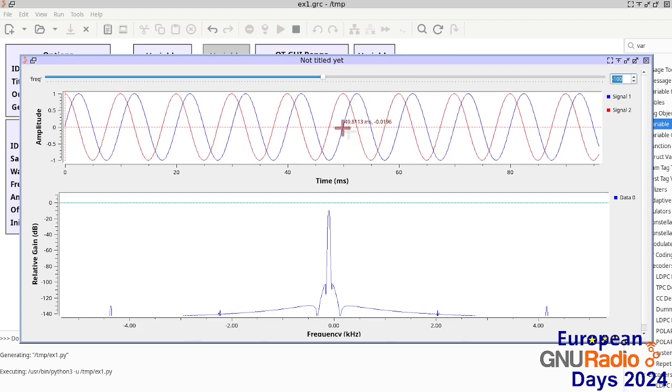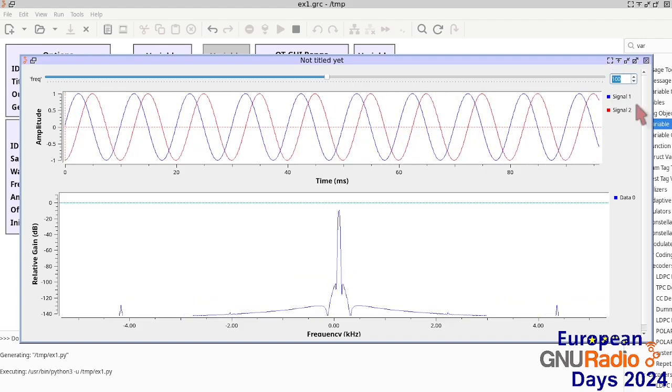So we have something which is a cos plus j sine, which matches the algebra of a complex quantity. And we see that a negative frequency is when the imaginary part is later than the real part, and a positive frequency is two voltages where the imaginary quadrature component is before the real part.